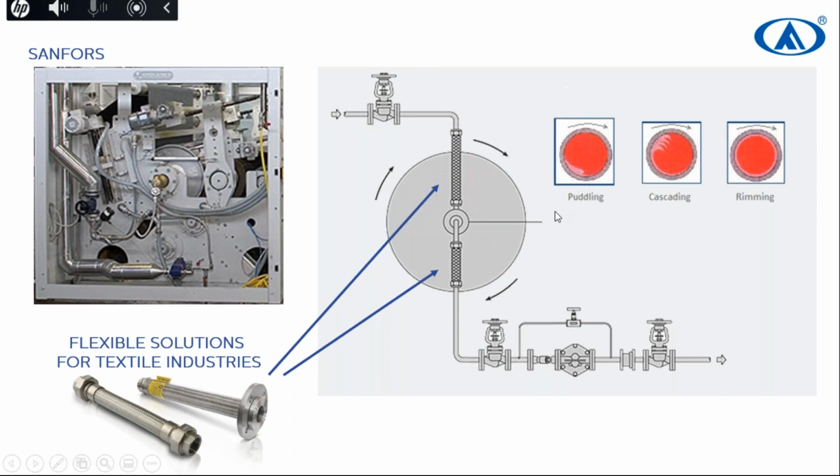And because of water hammer and water dragging, there will be leakage, there will be damage. To prevent it, we kindly advise to use the flexible metal hose in the same line, not in elbows. Turn it with some elbow, T connection, etc.